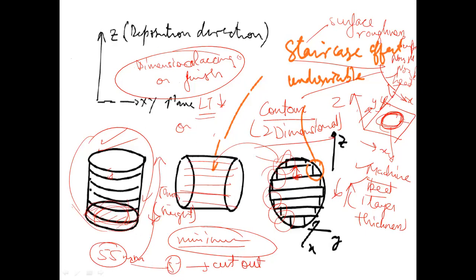So post-processing is definitely needed in order to minimize the effect of orientation. When you have an orientation and a bottom layer getting deformed, one solution is that you increase the height of the component and go for post-processing in order to get the uniform object.